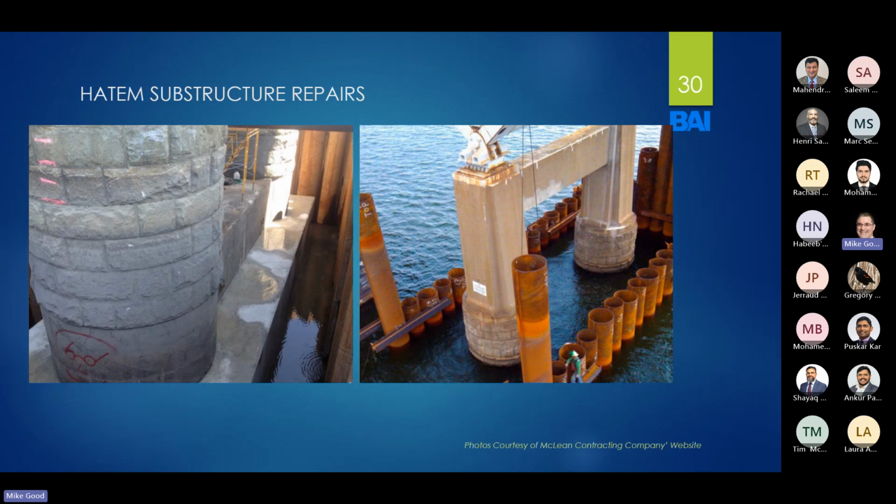And in this case, what we ended up doing was taking pipe piles and welding sheet pile connections to them, the kind of fist and knuckle connections the sheet piles use. And so these are interlocking circular piles. The circular shape makes them much, much stronger and able to withstand that loading.